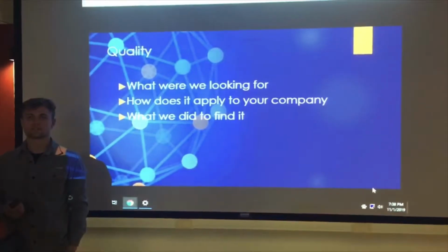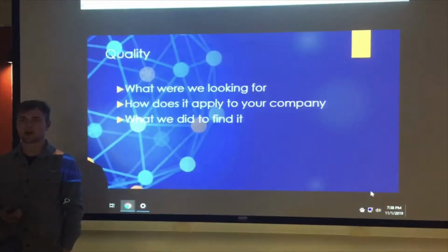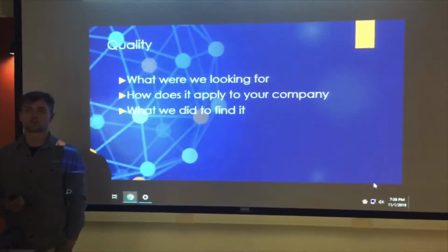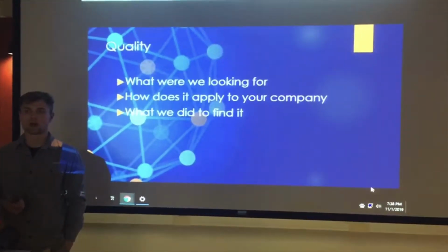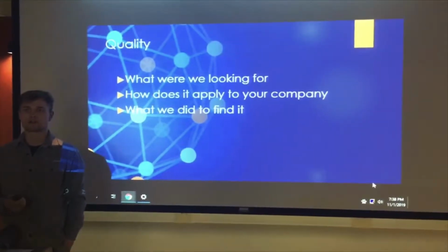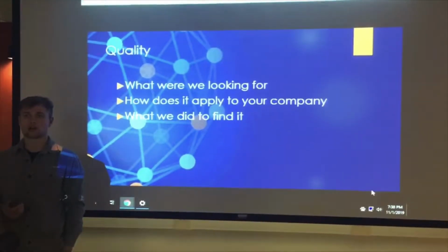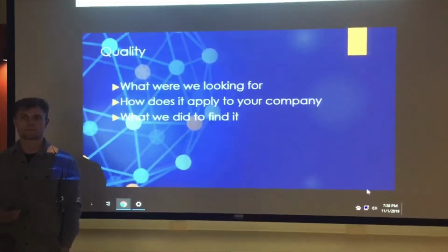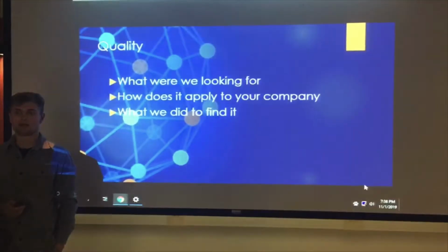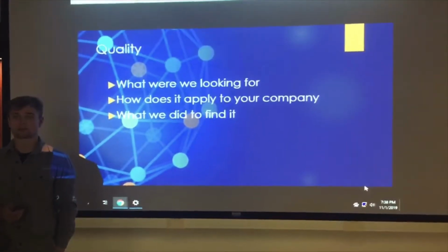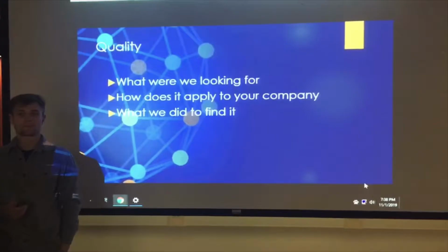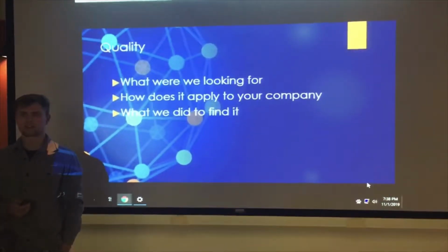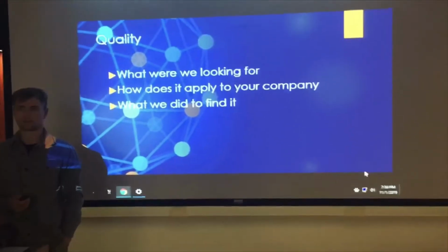Wing twisting plays a vital role in the structural mechanics of an airplane wing. This form of deformation causes premature failure in the structure that otherwise wouldn't have occurred. Understanding where to concentrate shear on an airfoil can completely cancel the resulting twist of the load. The shear center of a body is defined as a point about which the external load has to be applied, so that it produces no twisting moment. It is clear that the determination of the shear center would yield worthwhile results.